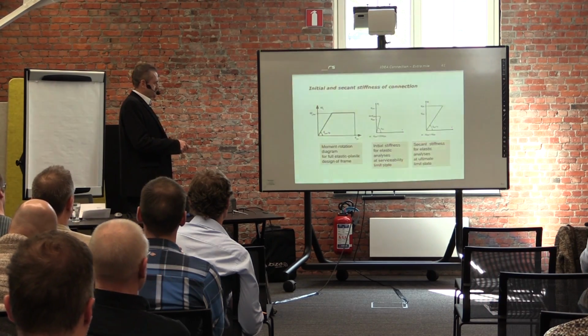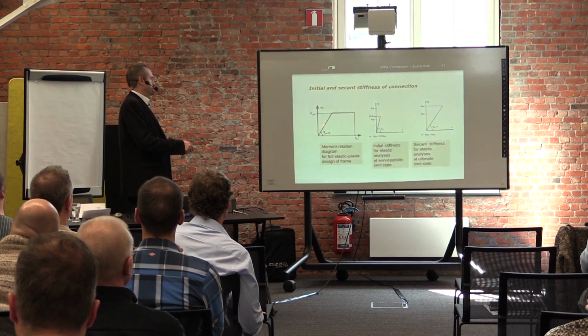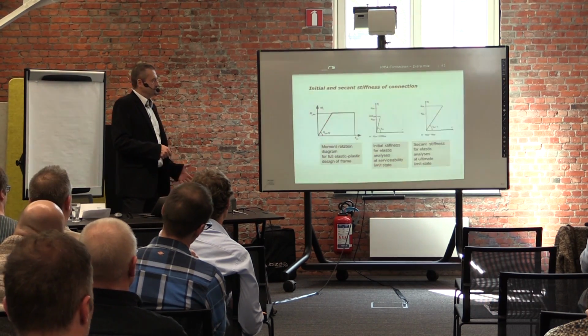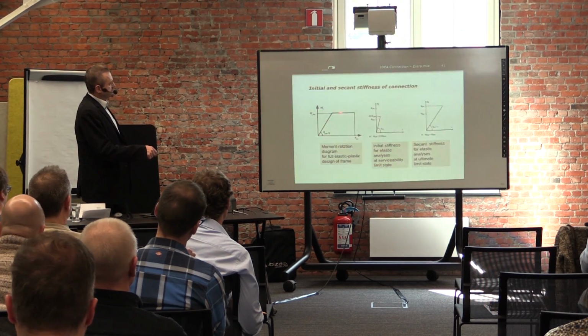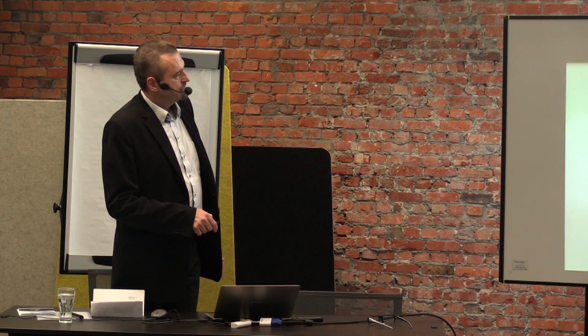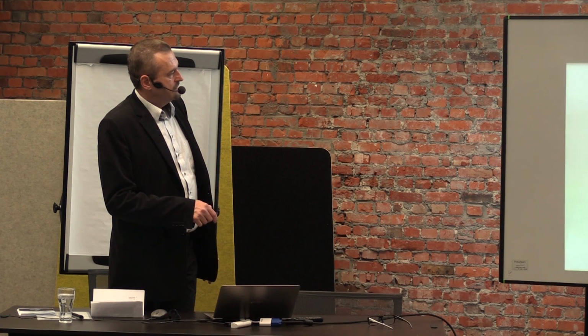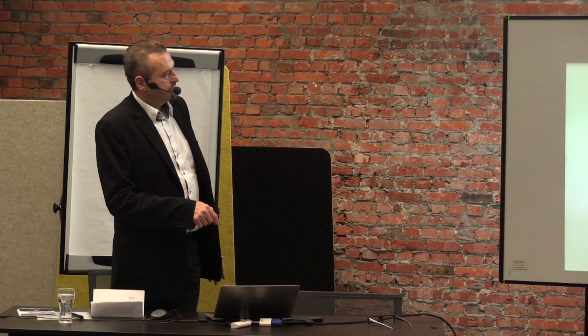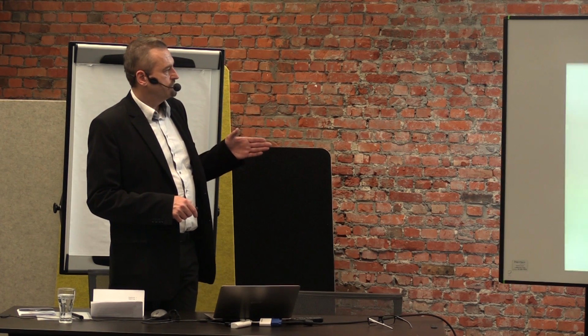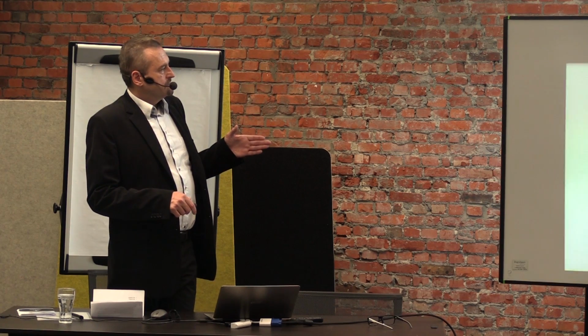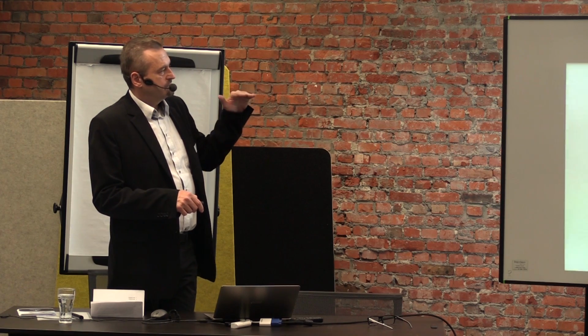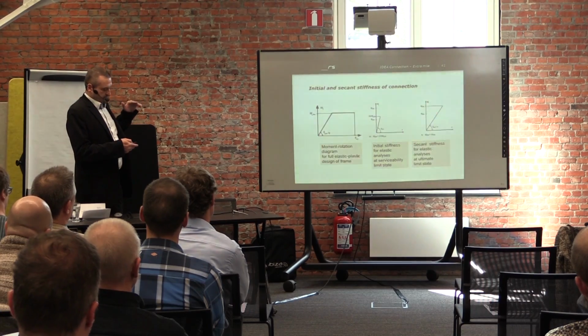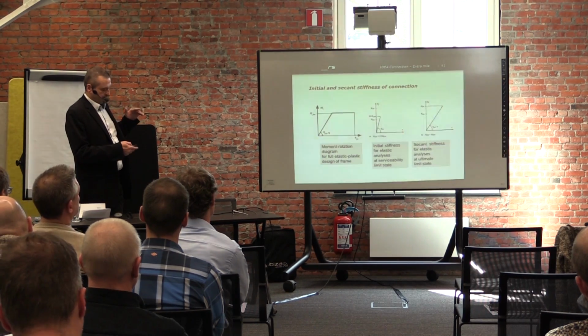Only to remind, the theoretical stiffness normally used in codes is bilinear. So we can analyze some initial stiffness, which is usually used in the global analysis of a frame, or you can calculate the secant stiffness for a specific level of loads. In CBFEM we calculate the secant stiffness.